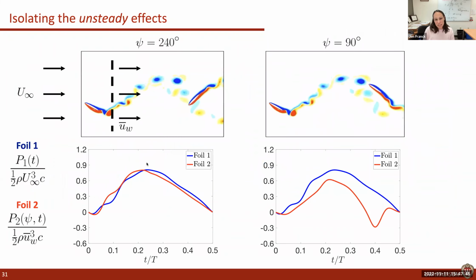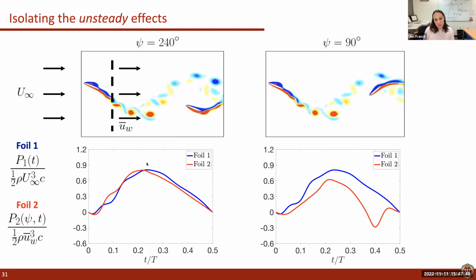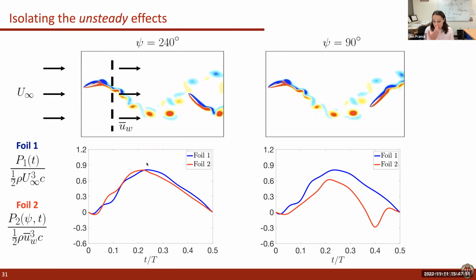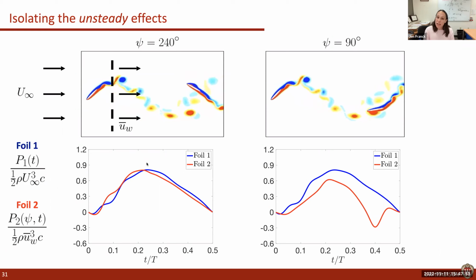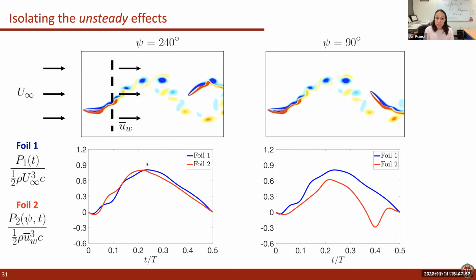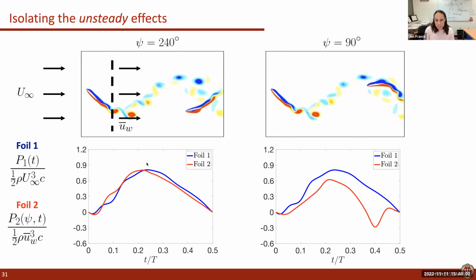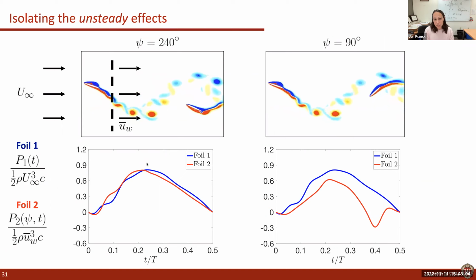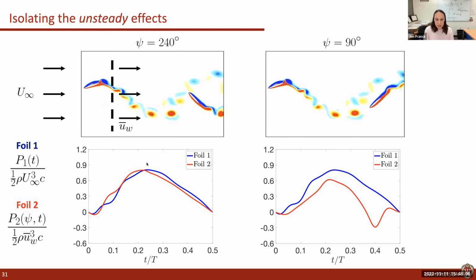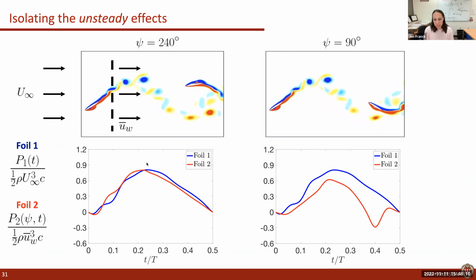If you imagine this system is a tandem configuration, so we're forcing the second foil to be directly behind, in the same swept area as the first. If you stagger it, so if the second foil is allowed to go slightly above the first foil in terms of its swept area, it is then in a position that it can grab those vortices and use them constructively. But due to the configuration of this system, these are the limitations that we're seeing.